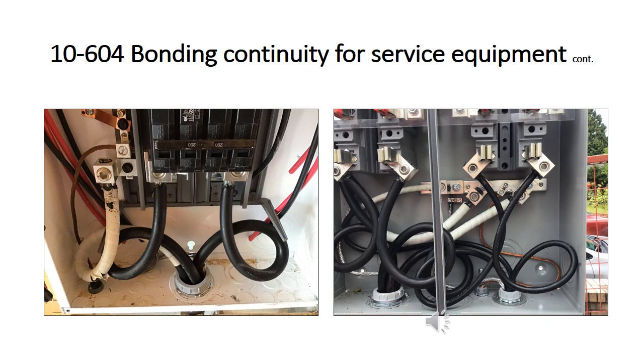And if you did not know the difference between TEC or ACWU, if you just looked at the two cables, how could you determine which cable is TEC and which one is ACWU? TEC has the internal rubber jacket around the conductors, whereas ACWU wraps their conductors in paper. That's how you can tell the difference between TEC and ACWU.